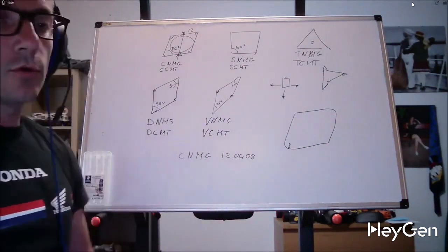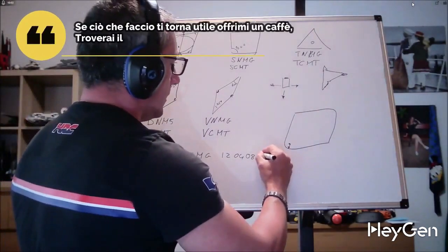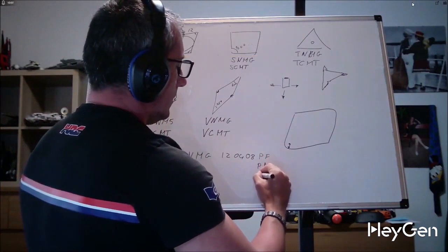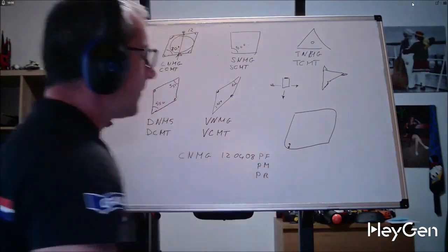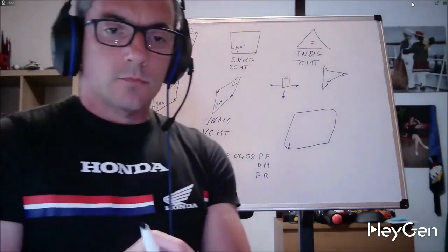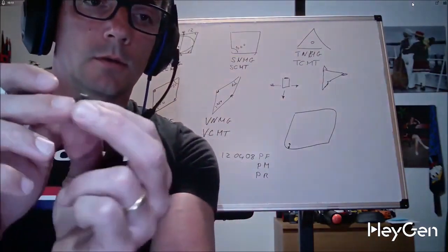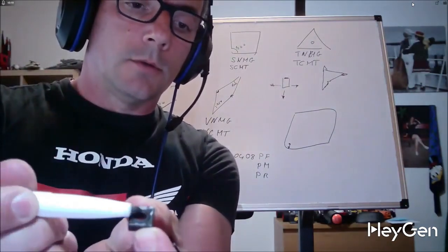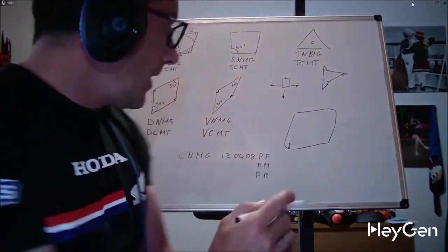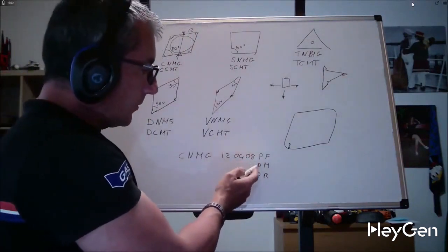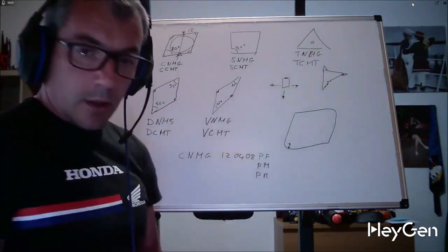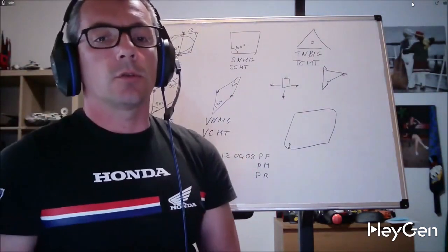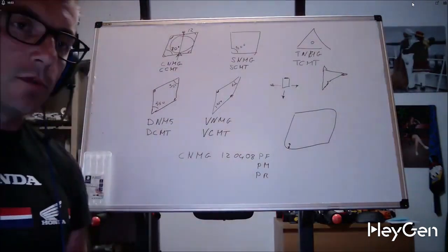I will give an example with Coromant because I know it well. PF, PM, PR define the geometry, the shape of this figure that you see above, which is called the cutting edge. PF are usually cutting edges for finishing, PM for medium roughing, and PR for heavy roughing. However, these are things you will need to learn from the catalogs, along with your tool supplier.